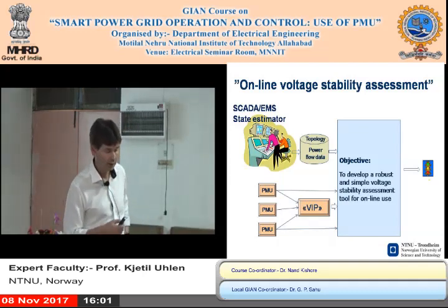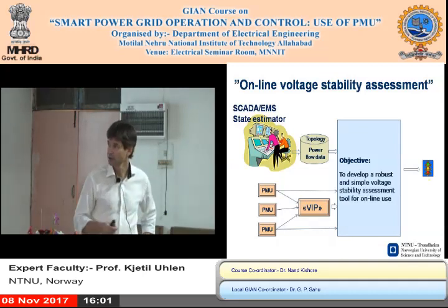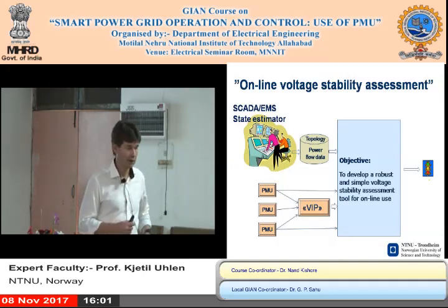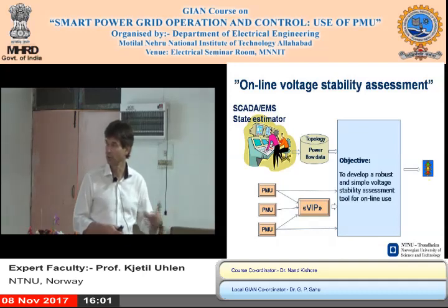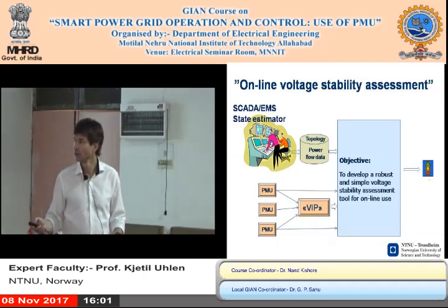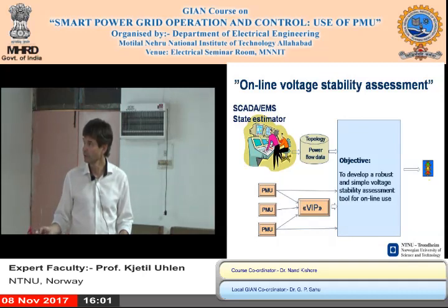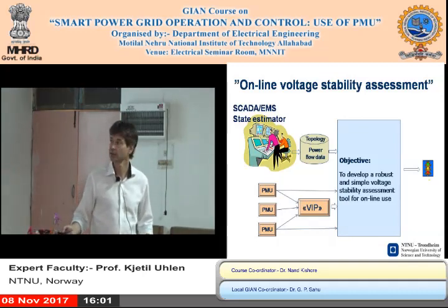That is good, but in an online setting you need to get fast information. If the system changes suddenly, the SCADA EMS system is not able to update probably, so a useful addition to the EMS system would be to have some indicators based on PMUs in an online setting.